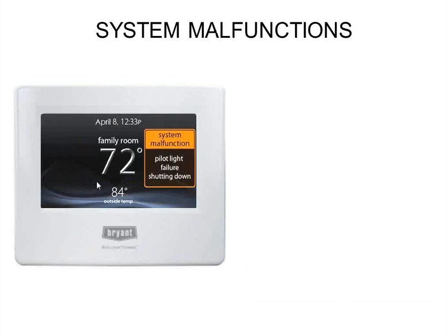If an error pops up, and hopefully you don't get a pilot light error, this is just a little joke we have on here, but you'll get an error off a piece of equipment. That equipment monitors dozens of different variables, and it can communicate that back to you. So not only does it tell you there's a problem, it'll tell you the specific problem. Like you have an igniter fault, you hit the high temperature limit, you are exceeding the airflow static pressure limitations of the unit, your filter is dirty. It's actually measuring these things in the unit and communicating to the circuit board in the unit, so it knows the safety reason that this thing was shut down, and it'll tell you the specific reason why it's shut down.